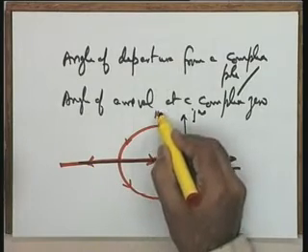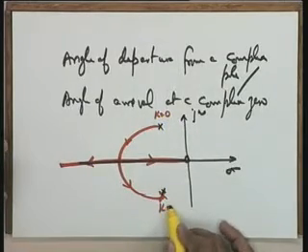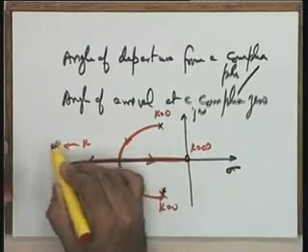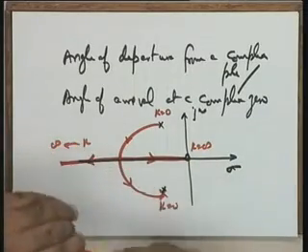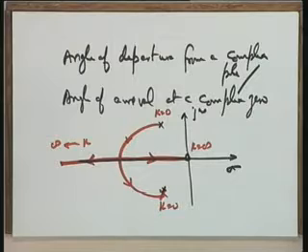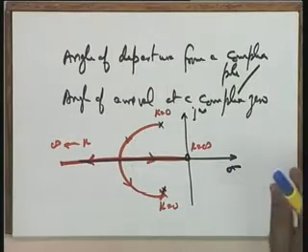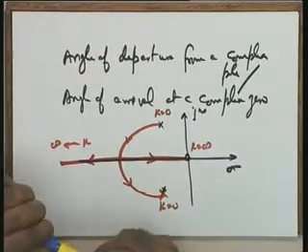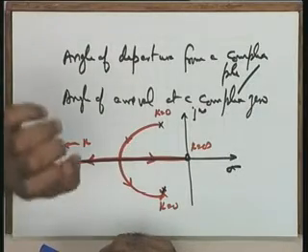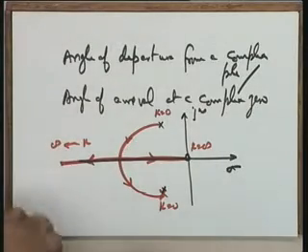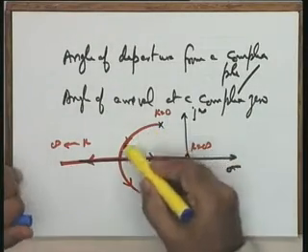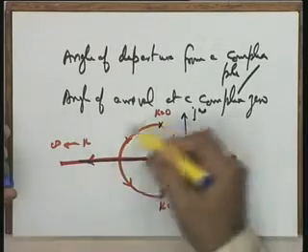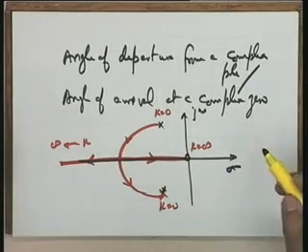Let us say k is the root locus gain, k is equal to 0 here, and k tends to infinity here. This is a root locus sketch which is already there in your notes. Now the question is this: in this particular sketch, fortunately it can be proved, rather I would like to leave this as an exercise to you to prove, that this complex root locus portion is a circle.